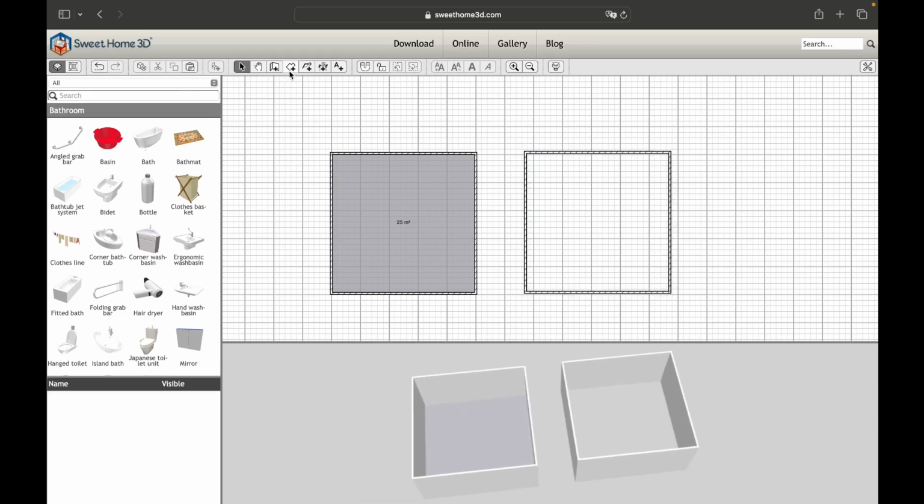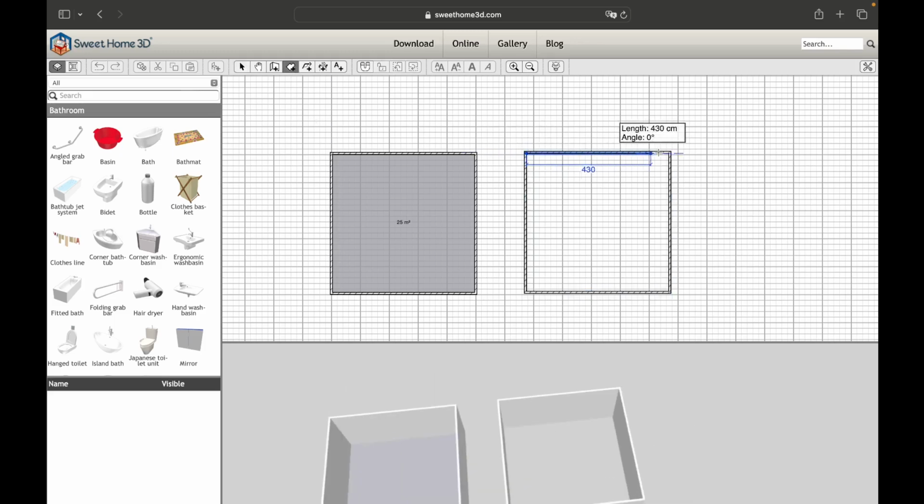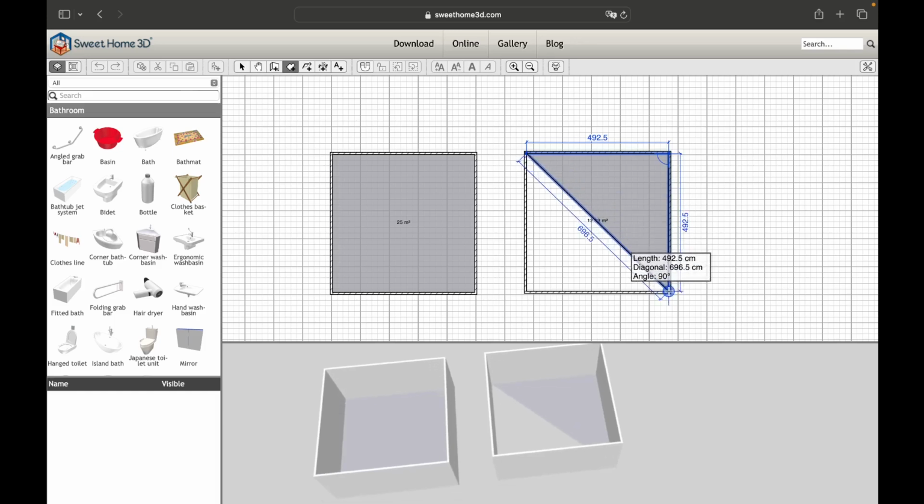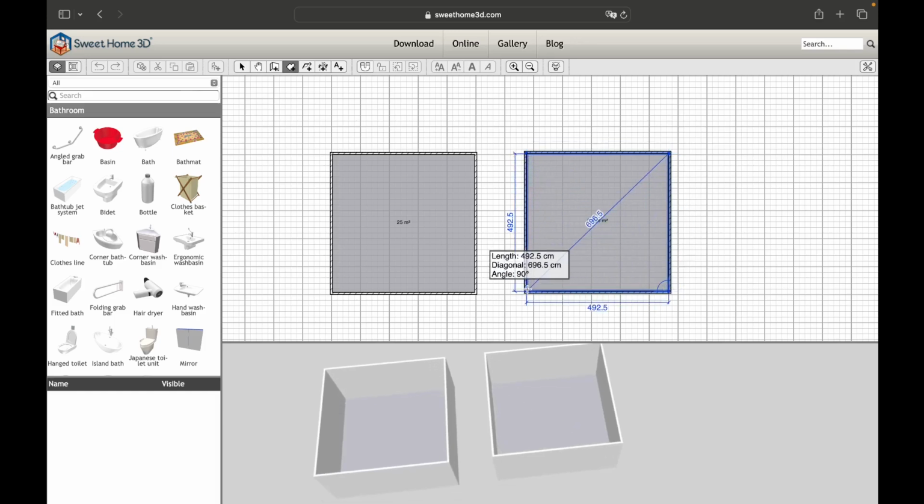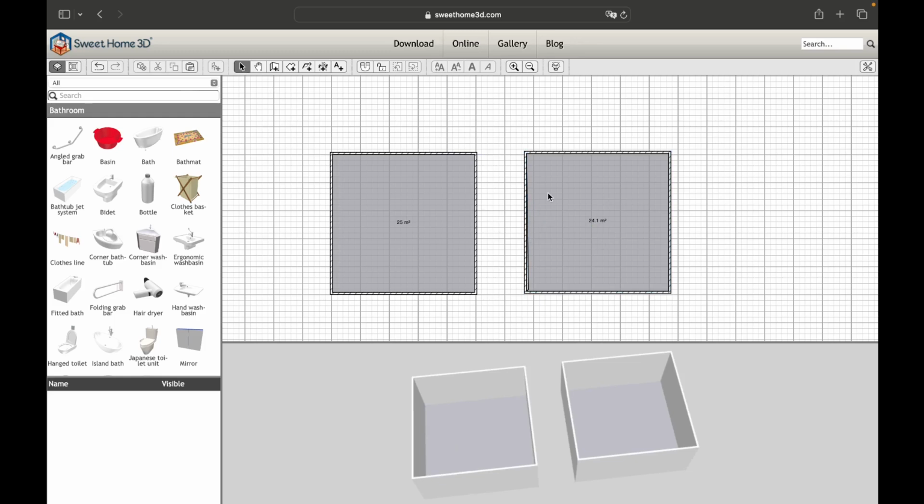This is because by not paying attention, we could create the internal surface of the built walls, which, as we can see, does not correspond to the desired size. Therefore, I strongly recommend building the flooring first and then the walls, or keep in mind to create the surface by clicking on the external edge of the created walls.